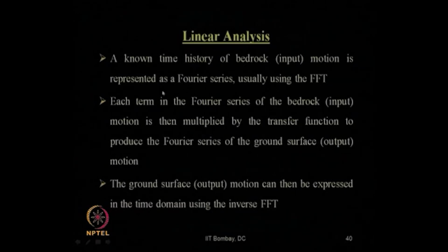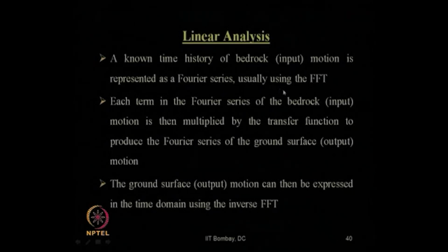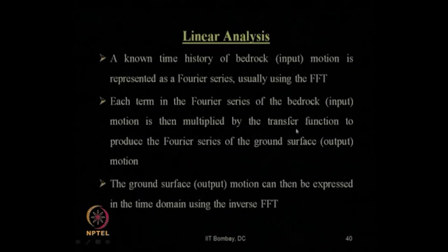You can express that mathematically in terms of a Fourier series, usually by using the fast Fourier transform. Each term in the Fourier series of the bedrock input motion is then multiplied by a factor called the transfer function. What is a transfer function?